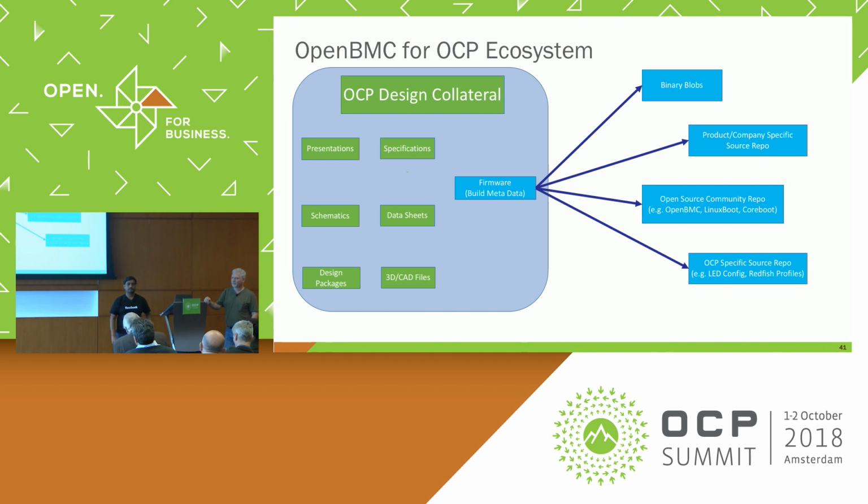For storage systems, I understand the BMC is just controlling the box fans, right? Correct. Everything's done in-band for storage systems. No, today, but even storage people are thinking about out-of-band management, like NVMe-MI, for example. Right, but that requires SMBus and MCTP support in OpenBMC, which is on your sometime-in-the-future list, right? True. And part of it requires you to put MCTP support in Linux itself, right?